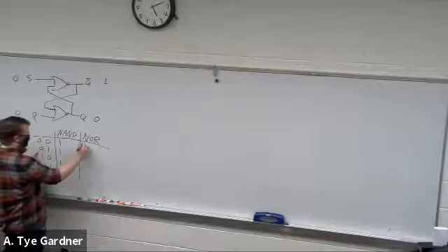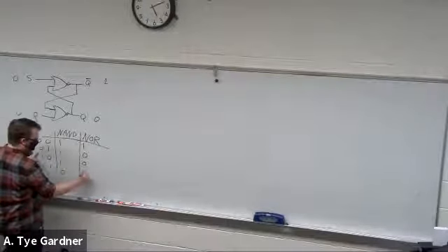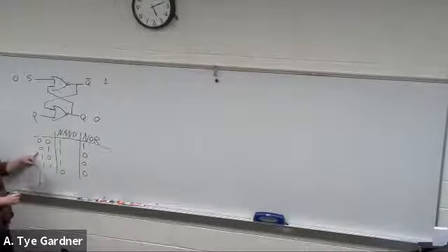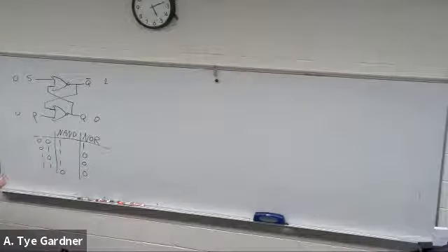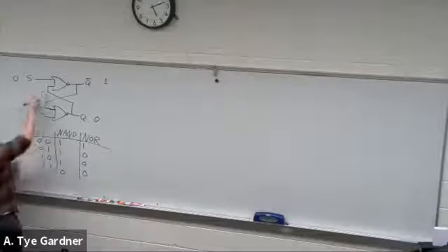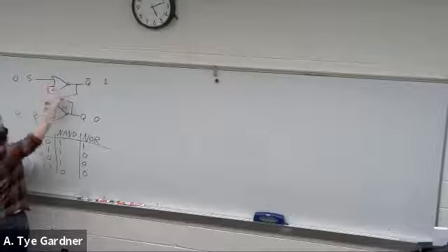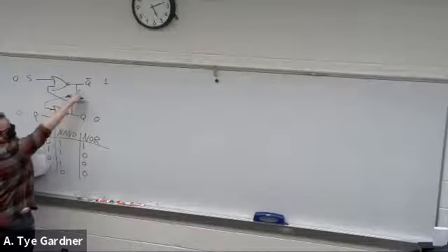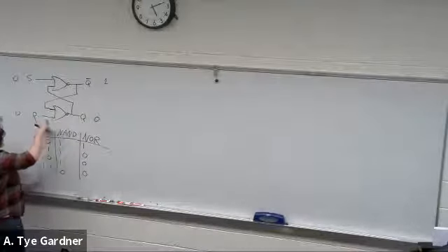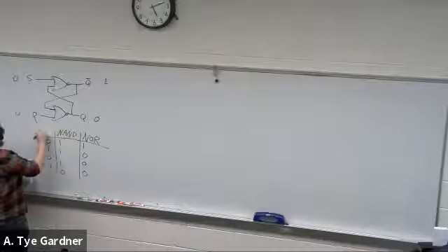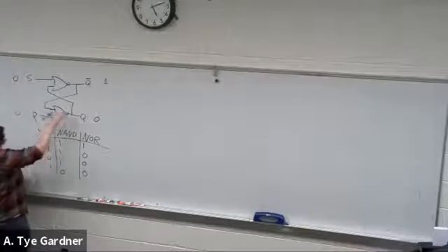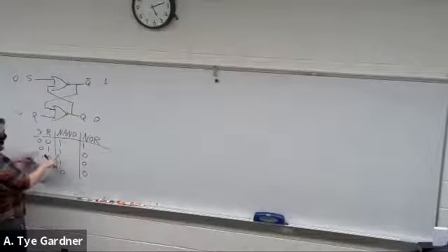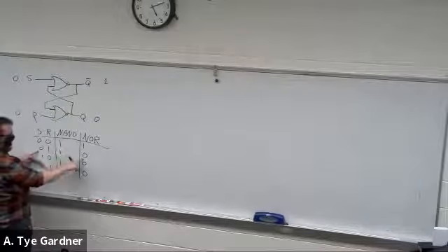Instead it's 1, 0, 0, 0, right? Now again, we'll start with Q is 0, the two inputs are 0. So set 0, 0 is 1. Great. Now we have Q bar feeding back, which is 1 and 0. Let's call this set and reset here. 1 and 0 is 0. Great, there we go.